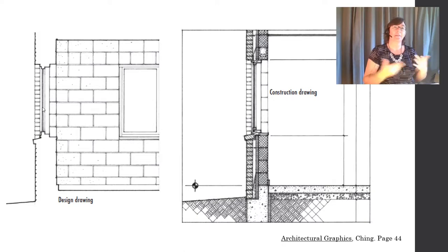So let's take a look at some examples of some technical drawings and how we use line weight in these drawings to aid in communication. And you can see on the left, we've got a drawing with a profile line in a very heavy line weight right here. So we can easily tell that we are actually cutting through this item. And then these surface lines indicating the materiality of that far wall are a much lighter line weight.